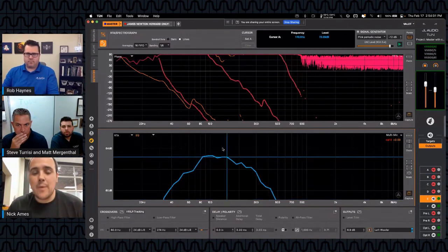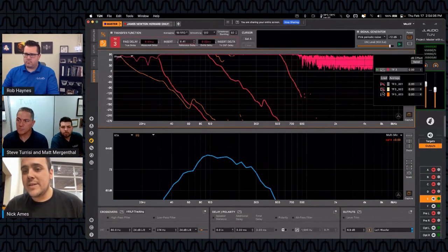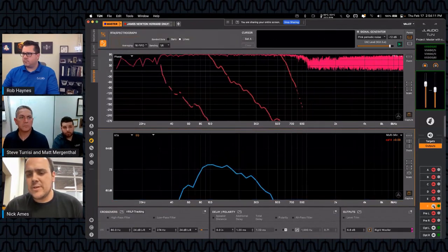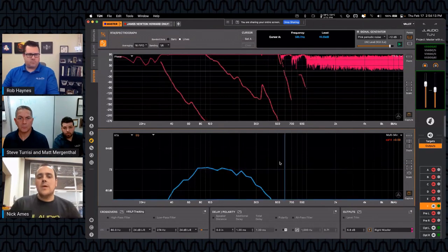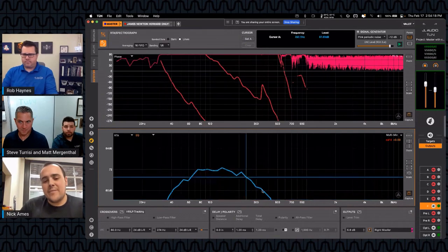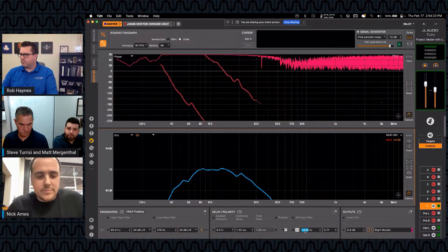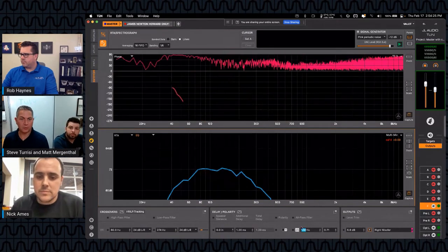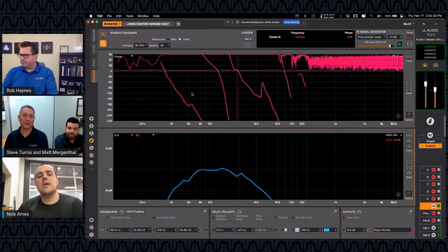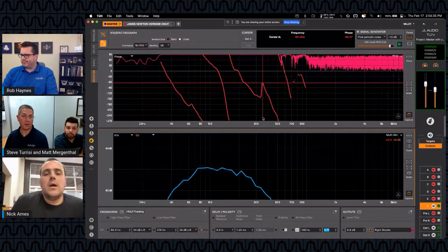And then that would be a mimic of what you sometimes have acoustically. Let me get these other ones up there. Sometimes acoustically, I think it's the near side, I always forget, one of the two mid-bass speakers will have an acoustic effect at, let's see, 148 hertz. Because this car doesn't seem to really need one, we're going to fake it. We're going to force it so you can see what it looks like in the phase domain and the resulting summation that you would get if there was an all-pass applied.